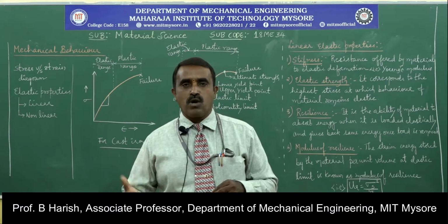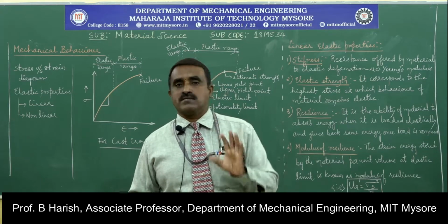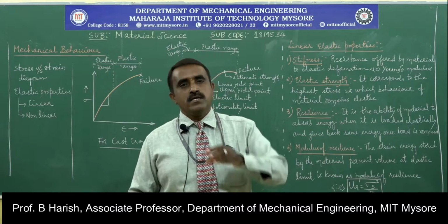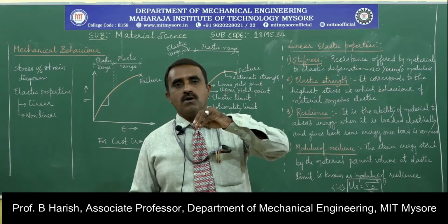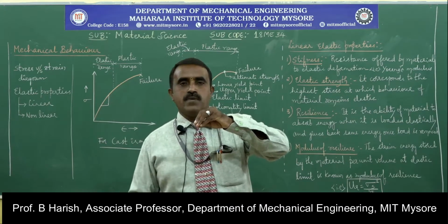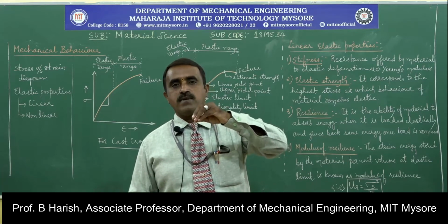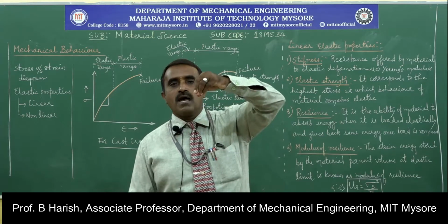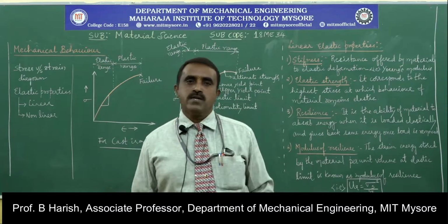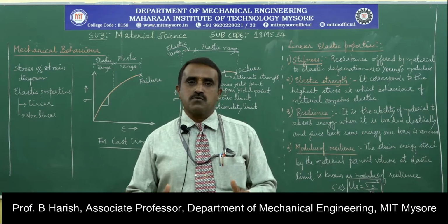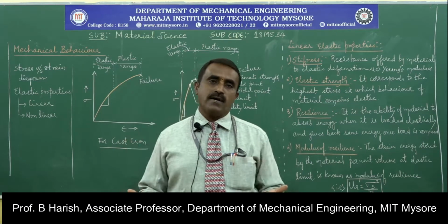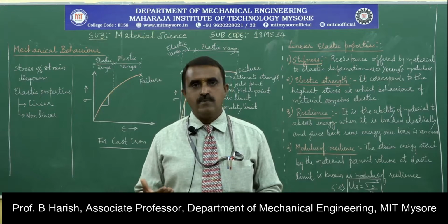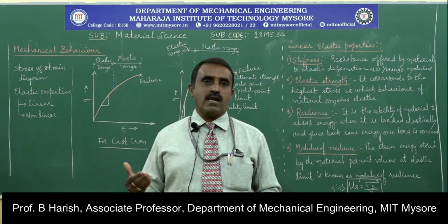Stress is the load we are applying. Strain is nothing but elongation. Both values are noted down. We continue loading and note down the values. At a particular interval of time, when maximum elongation takes place, the specimen breaks. Based on the values noted down, a graph will be plotted taking the stress and strain values.